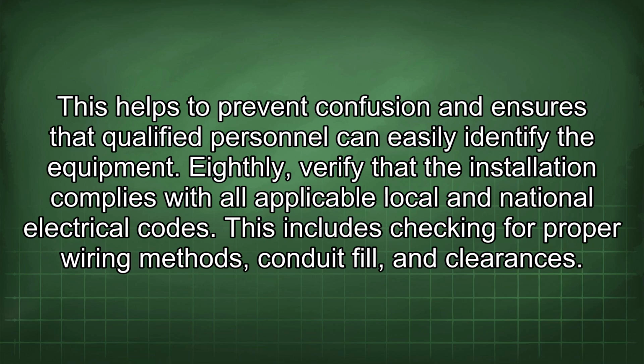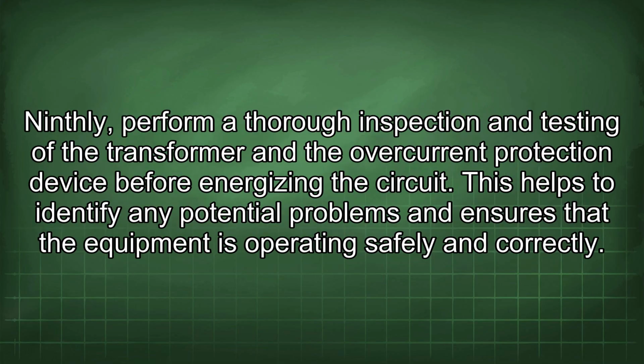Eighthly, verify that the installation complies with all applicable local and national electrical codes. This includes checking for proper wiring methods, conduit fill, and clearances. Ninthly, perform a thorough inspection and testing of the transformer and the overcurrent protection device before energizing the circuit. This helps to identify any potential problems and ensures that the equipment is operating safely and correctly.